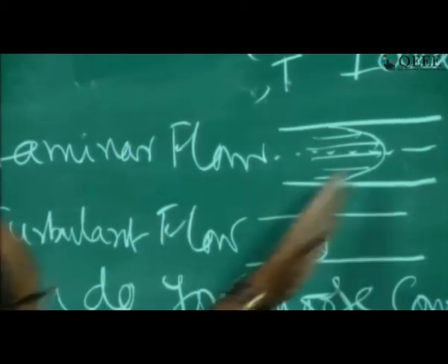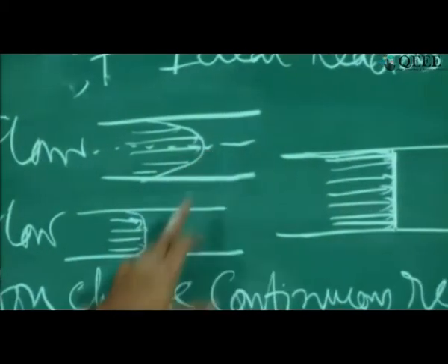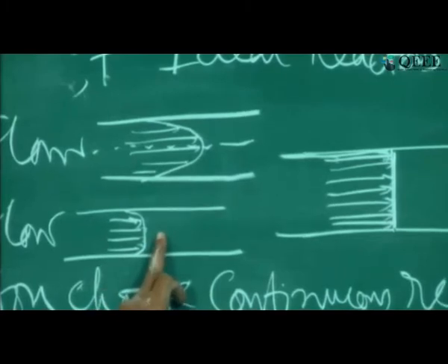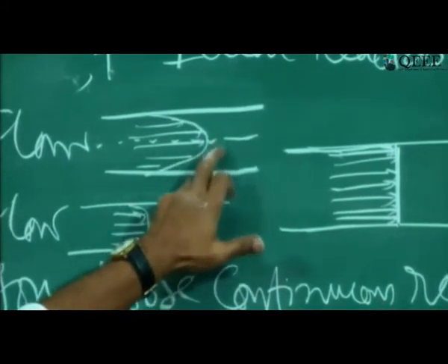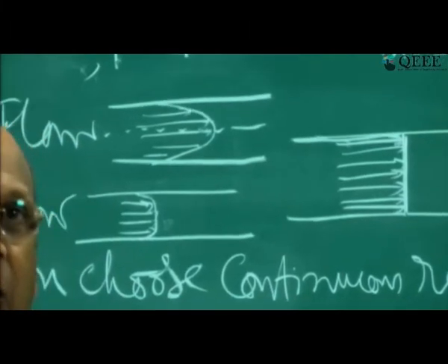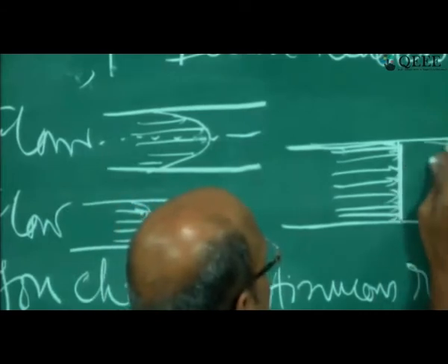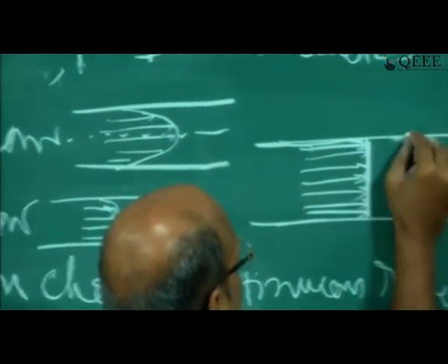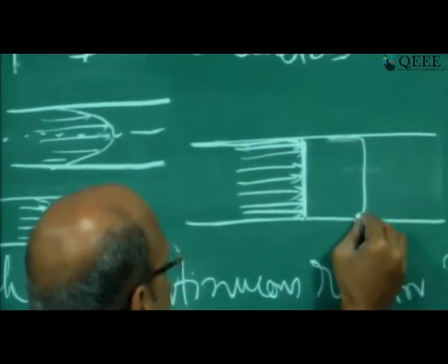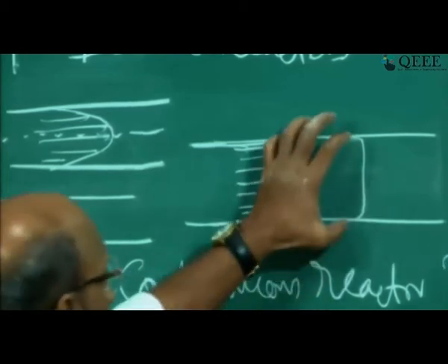Yeah. But what we are defining is even beyond these two. What we are defining is this one laminar flow, this is turbulent flow, and if I ask you the Reynolds number, you will tell that this is less than 2100 laminar flow, and here you have turbulent flow can be 20,000, 30,000 like that. But if you go to 100,000, probably you will get something like this. This is very close to plug flow. So this is what we are expecting in plug flow.